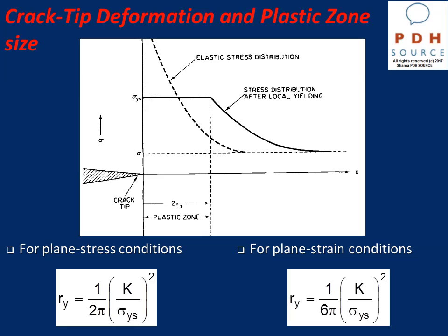The size of this plastic zone, Ry, can be estimated from the stress field equation and can be expressed for the plane stress conditions according to this equation and for the plane strain condition according to the second equation.